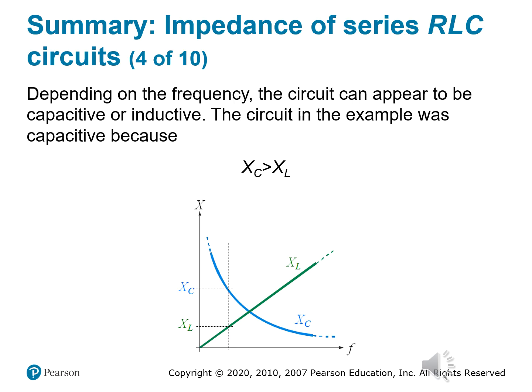Oh, well, here's the secret sauce. It's all about comparing the reactance of the inductor, X sub L, and the reactance of the capacitor, X sub C. So when X sub C is greater than X sub L, the total reactance goes negative, meaning the capacitor dominates. When X sub L is greater, the inductor wins and the circuit becomes inductive.